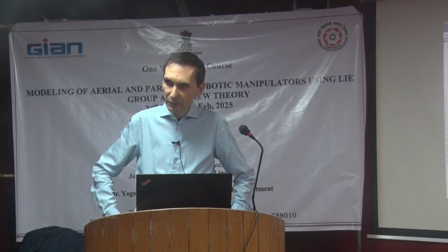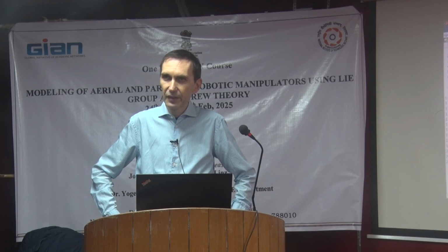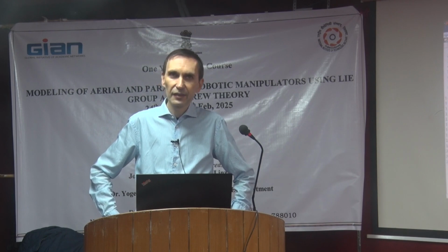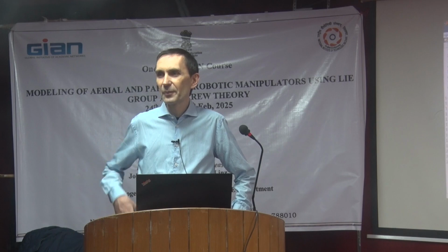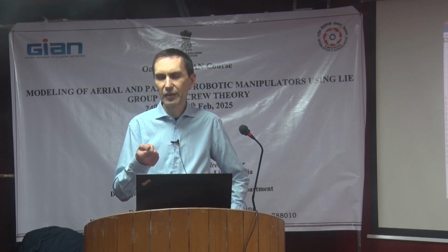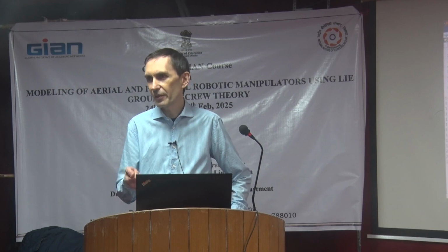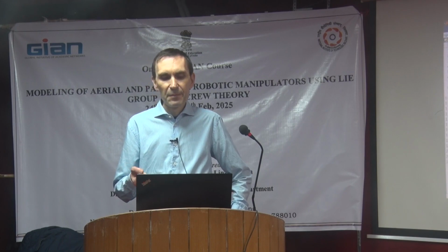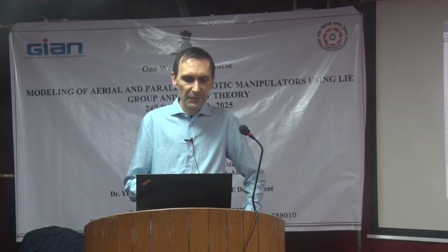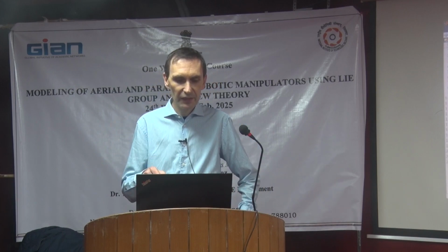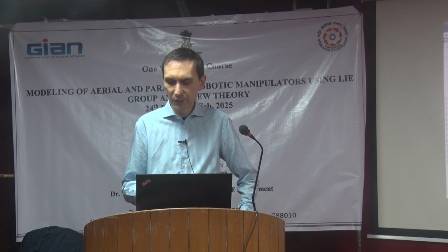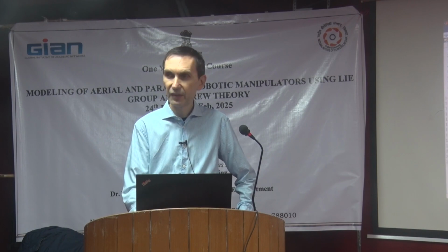A prismatic joint has an infinite pitch, and it's more like saying that you would need an infinite translation to get a rotation, which means you never get a rotation. And in this case, the screw coordinate looks different, because then the screw coordinate is just the unit vector.